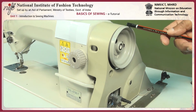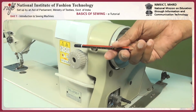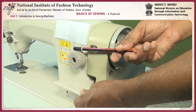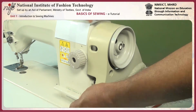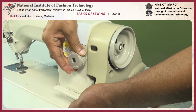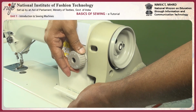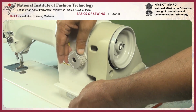This is the hand wheel. This one is the SPI regulator. The purpose of this instrument is to increase or decrease stitch length. How to operate this one? It can be operated clockwise or anti-clockwise. Now I will operate it. It can be operated like this. If you want the stitch length to be longer, rotate it anti-clockwise, and if you want the stitch length to be shorter, rotate it clockwise.